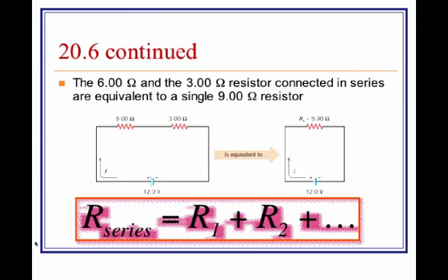When solving problems with circuits, the first step is to reduce the circuit down to the simplest form, and then go back from there and solve for the current, and then reverse back up using the branches. So here we have a 3 ohm and a 6 ohm resistor connected in series. This is equivalent to one 9 ohm resistor. This is the equivalent resistance of those two.